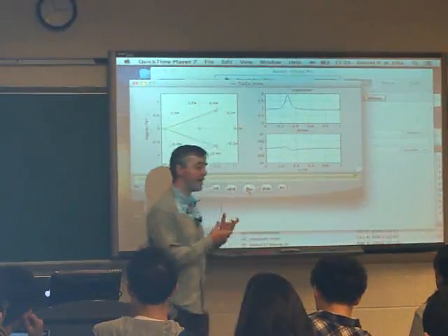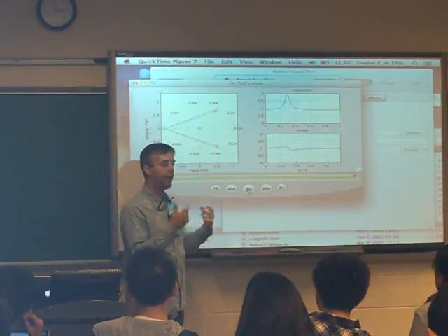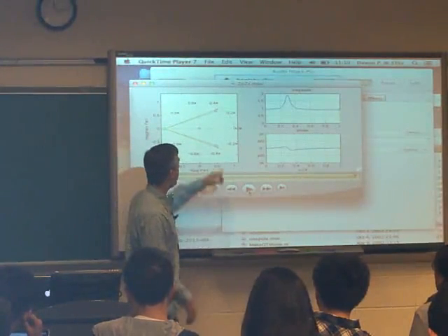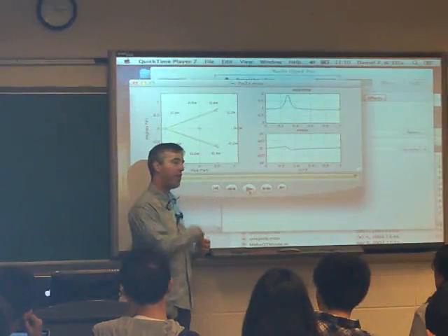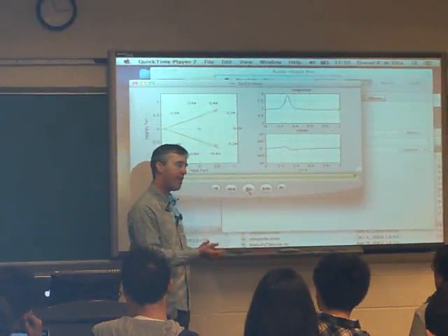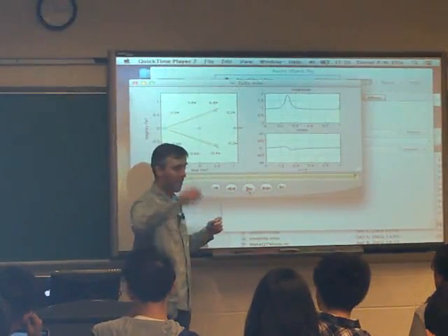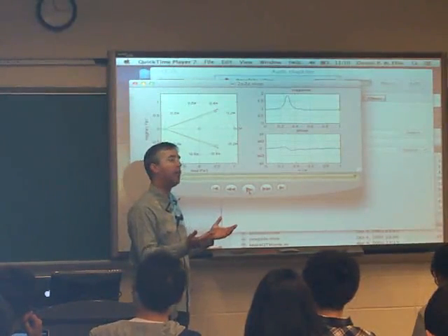But that's the same as this concept of the highest frequency that we can represent without aliasing in the time domain, which was called the Nyquist rate. That if we have a sinusoid that advances by more than pi radians per sample, meaning it does more than half a complete sinusoidal cycle every sample, then it looks like a lower frequency sinusoid.